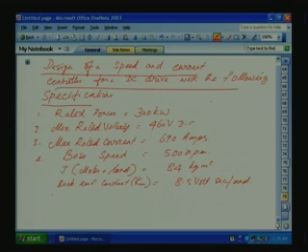Armature resistance Ra is equal to 0.02342 ohms and La is equal to 0.7026 millihenries. Let us take our converter we are using: a three-phase fully controlled thyristor bridge.